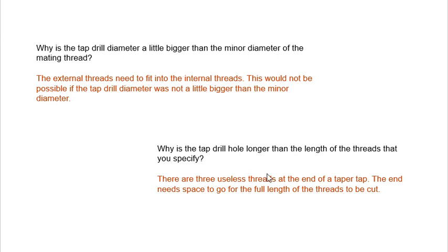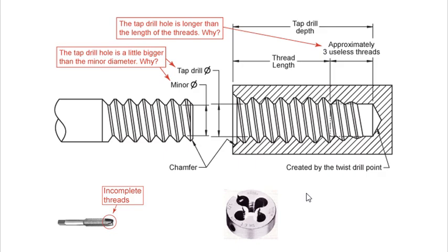We always leave some space like that because you're dealing with metal, okay? Metal usually expands, so if you don't leave the space, it's gonna mess up with the expansion, especially when the temperature of your environment increases. So therefore we usually give a little space like that and a little space like that for them to expand.